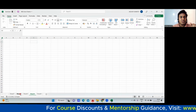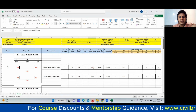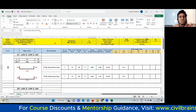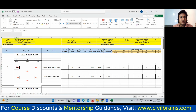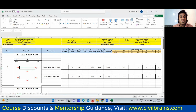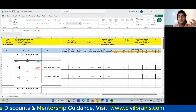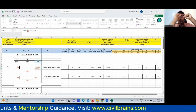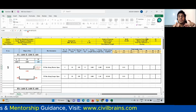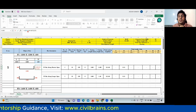So if that is the case, come to Excel sheet. Bend deduction, anyhow, I applied the bend deduction. Here you can see the bend deduction minus 4 times I have applied it. This depth, whatever you have taken, they are telling to take it complete depth. That means instead of multiplying this by 2/3, whatever answer you are getting, that is overall depth minus top cover minus bottom cover, and whatever answer we got, we used to say 2/3 of that, because that is a general construction practice what we do.